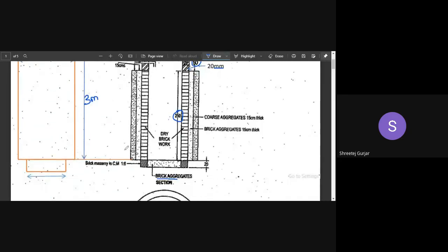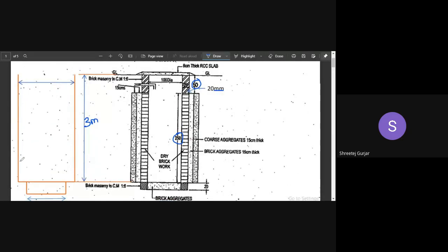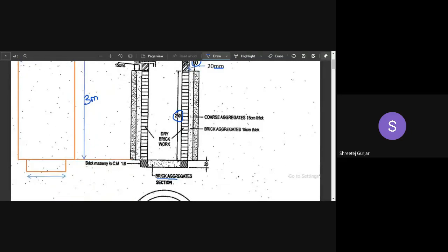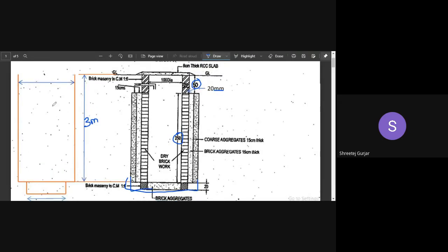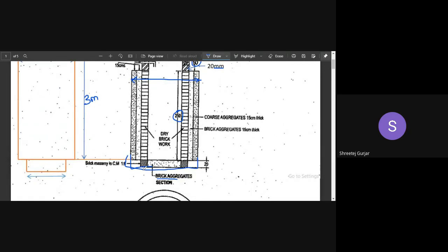Okay. So now we will excavate, as I've shown you, this part, and we will excavate this part over here. Not the entire thing. Like this we will not excavate. Why excavate extra when we only need this part? So that is why we'll excavate only this part. As you've seen over here in the left hand side, I've shown you the excavation that is exactly needed. So now we have to excavate from here till here. So that dimension we need, and we need this dimension.